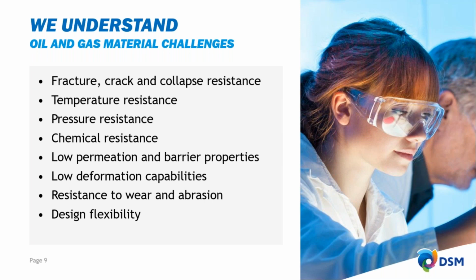So when we look at different depths, whether it be a shallow well at 4,000 feet, up to a deep well going beyond 7,000 feet, those pressures and the different chemical environment, hydrogen sulfide, and whether it be a high water cut versus a low water cut well, that takes its toll on the plastic materials for rod guides. Also, when we look at different wells, whether it be sour gas, temperature is definitely important.